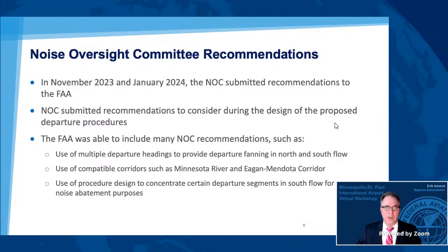Number 1, use multiple departure headings to provide departure fanning. Number 2, use compatible corridors such as the Minnesota River and the Egan-Mendota corridor. And number 3, design procedures that concentrate some departures to the south for noise abatement purposes.